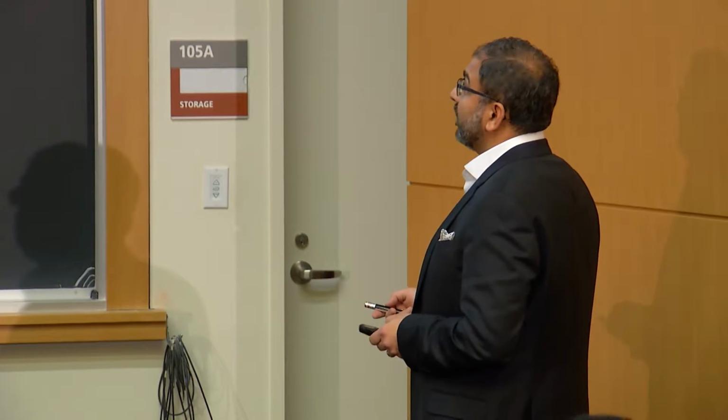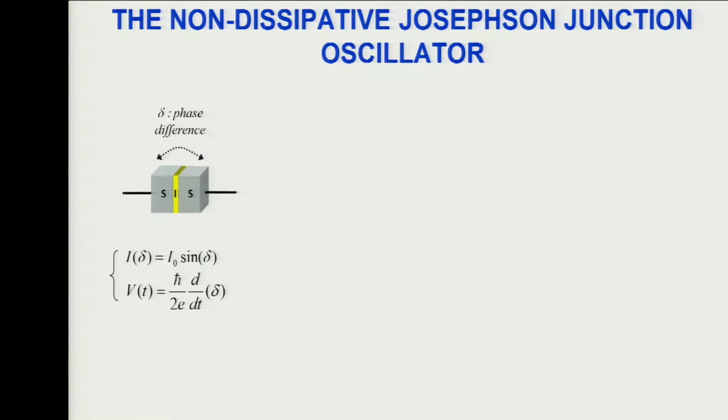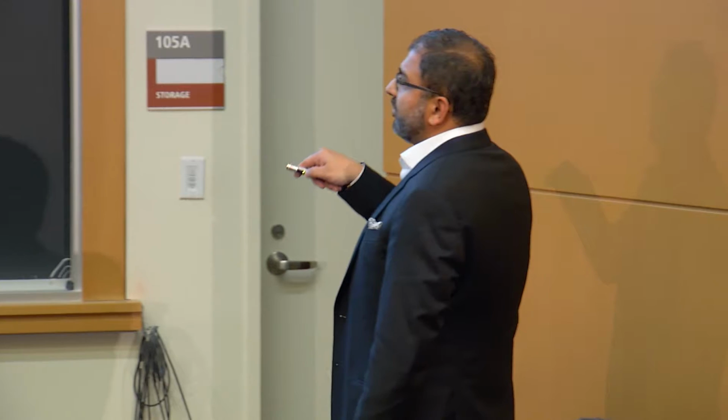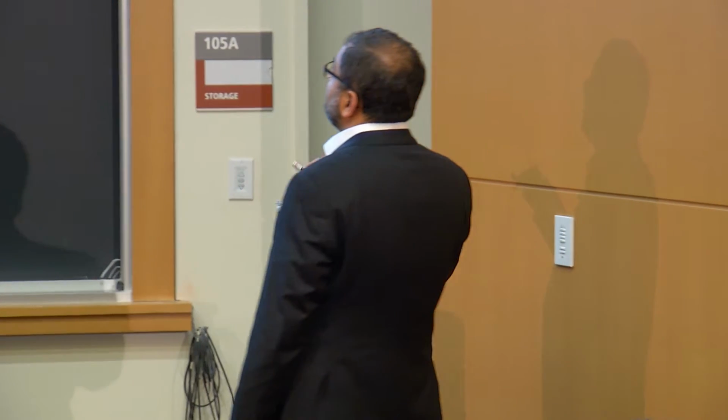We've known for some time, of course, from the time of Brian Josephson and all the talks that we heard about today, that the tunneling junction, as exemplified by two superconductors separated by an insulator, is given by this characteristic relation where the current is really the sine of the phase difference across it, combined with the voltage relation that gives us something with this type of cosine potential. And indeed, if the height of this potential is chosen such that there are only a few quantized levels, we can talk about qubits. And in fact, if there are many such levels, we can talk about a classical anharmonic